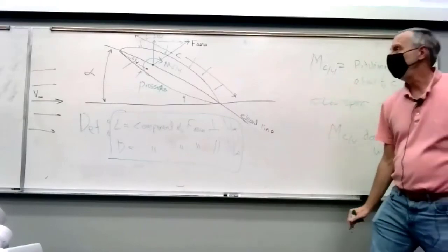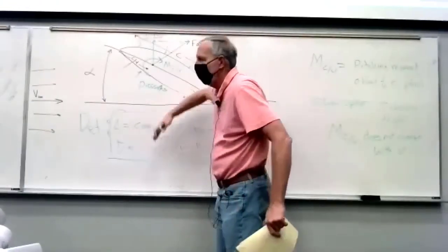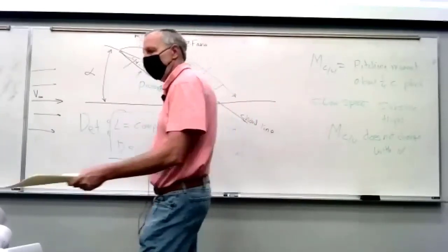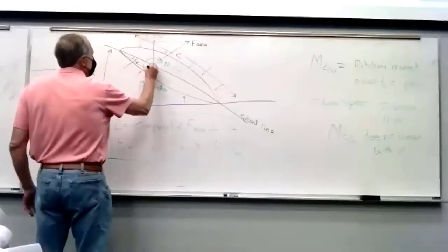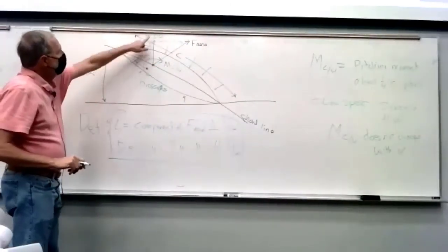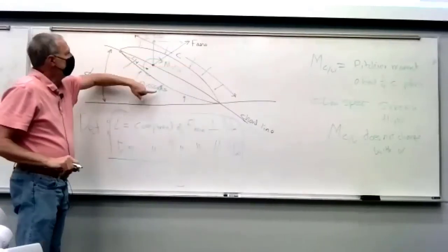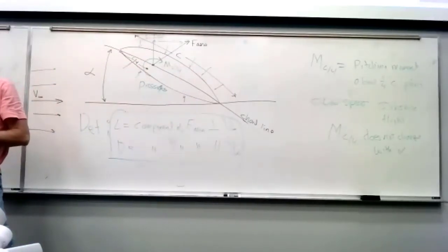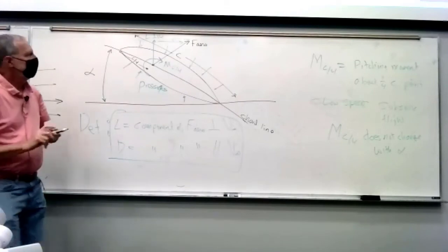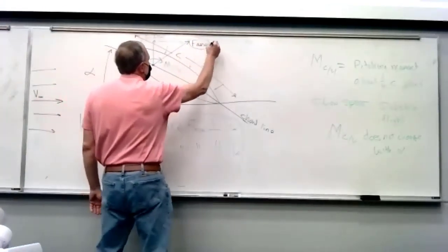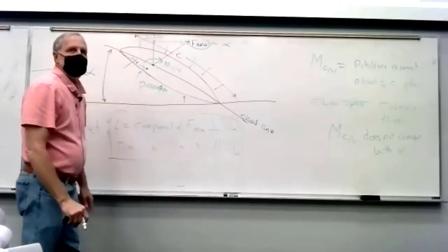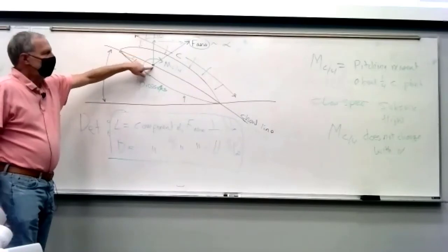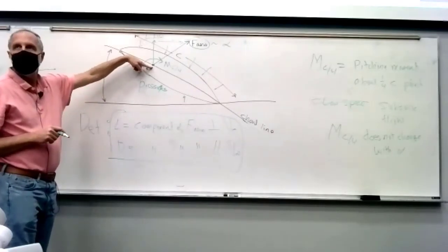And that's really nice. That means we just know this is a number, and whatever angle of attack we're flying at, that is the pitching moment we get, and we're good. And you can see that we're taking moments about this particular point, get that. And so the lift and the drag we draw acting at that point, and so changing the lift and changing the drag doesn't change the pitching moment because the moment arm is zero. Follow that? I'm drawing this aerodynamic force here. So the aerodynamic force changes with angle of attack. But because it's drawn at this point and we're taking the moments about that point, the moments don't change. F arrow does.